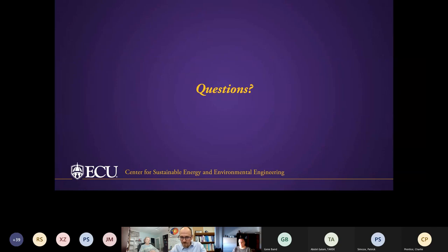Okay. And then another one, we did add aeration in the collection system to reduce aeration demands at the plant, determined it was a low-cost option, best for the biology of the whole system. That's cool. PFAS destroyed in a gasifier on the biosolids. All right, that's great too. Biosolids with PFAS gasified, destroyed the PFAS. Yeah, if you have a gasifier, that's amazing. And if it's working for PFAS, that's also excellent.